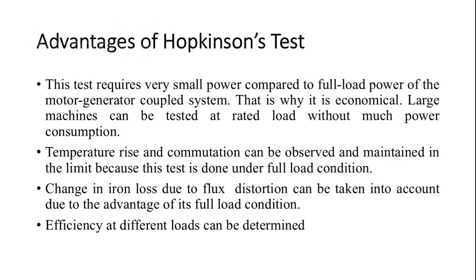Hopkinson's test is economical as it requires less power. It allows testing large machines at rated load with minimal power consumption. Temperature rise and commutation can be observed, and efficiency at different loads can be determined.